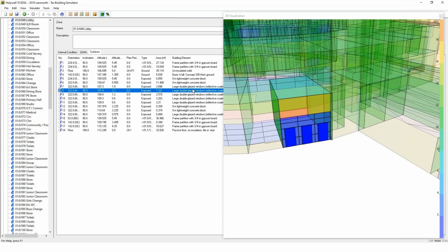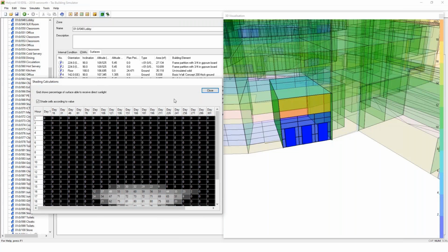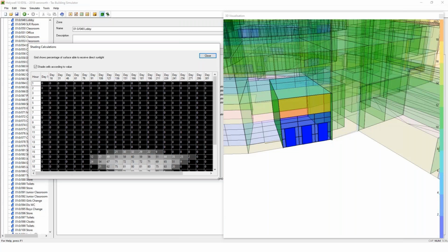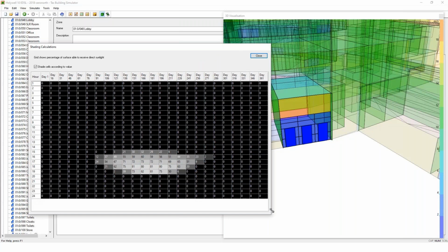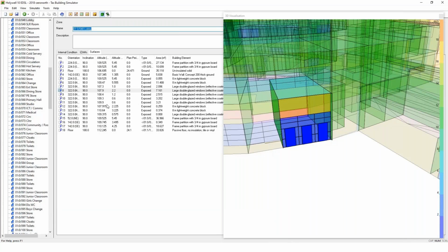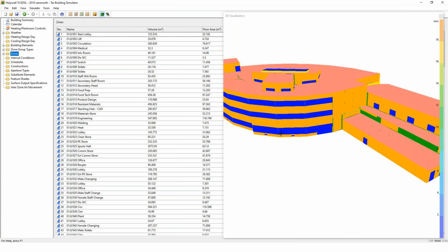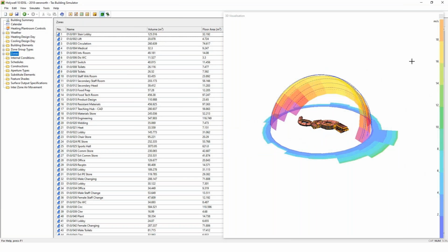These are done every 15 days. You can see right in the middle of the year, the direct is around 80 or 81% that is exposed without all these shading surfaces. So that's where we're at without accounting for the shading surfaces that are missing in this gbXML. But we still have a bunch of data in the model that can be kept.